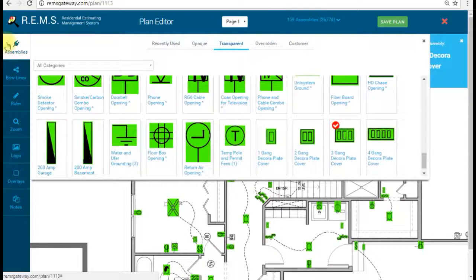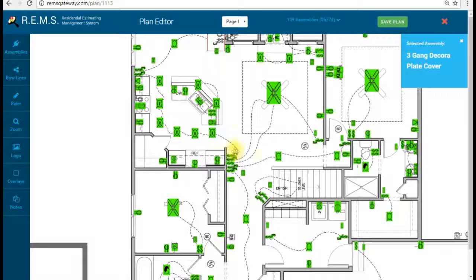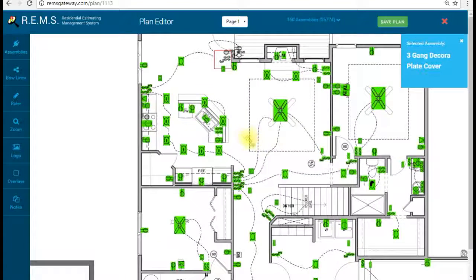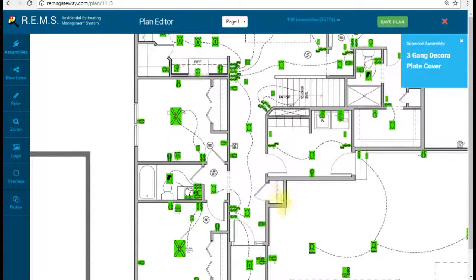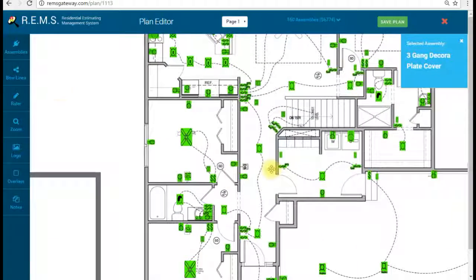They have it set at 5 switches here, so I'm going to switch this up to a 2 gang and a 3 gang and do some spacing on that. I'm not a real big fan in a house of trying to put all 5 switches in one box. If they request it, I do it, but I'm not a big fan of it.